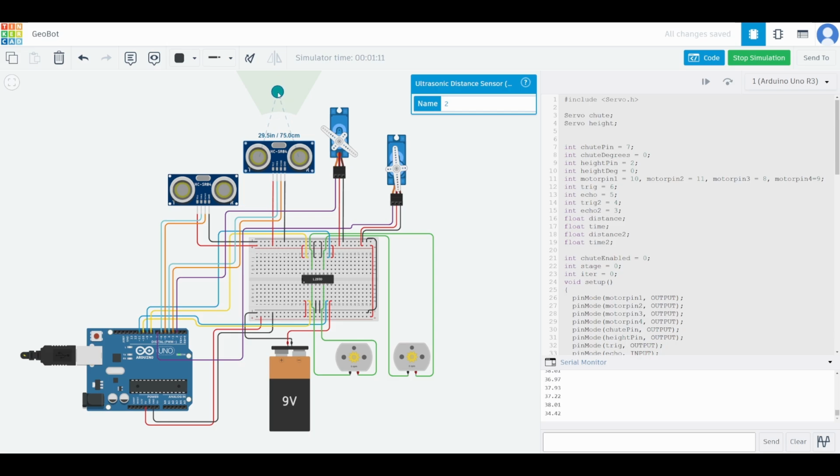But in this case, let's pretend that the object is in fact less than 12 inches. For a split second there, this servo, which represents my chute, which would deploy a puck, a GPS puck, goes to 90 degrees and then goes back to get ready for the next puck, and then it sends the geolocation data to the database of where the geopuck was placed.